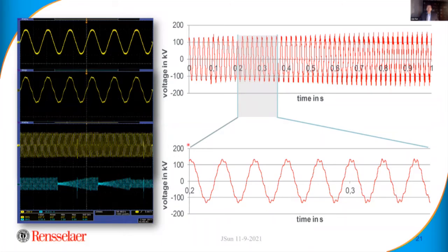What I'm showing on the right is an actual measurement in an offshore system. It shows in reality how resonance occurs. So these are steady state pictures. I see the waveform being steady state, but this is more of a transient where a configuration in the operation triggers an underdamped or undamped resonance, and that creates a harmonic that increases over time. So the harmonic grows, you can see the harmonic increases, right? And the frequency of the harmonic is not a multiple of the fundamental.